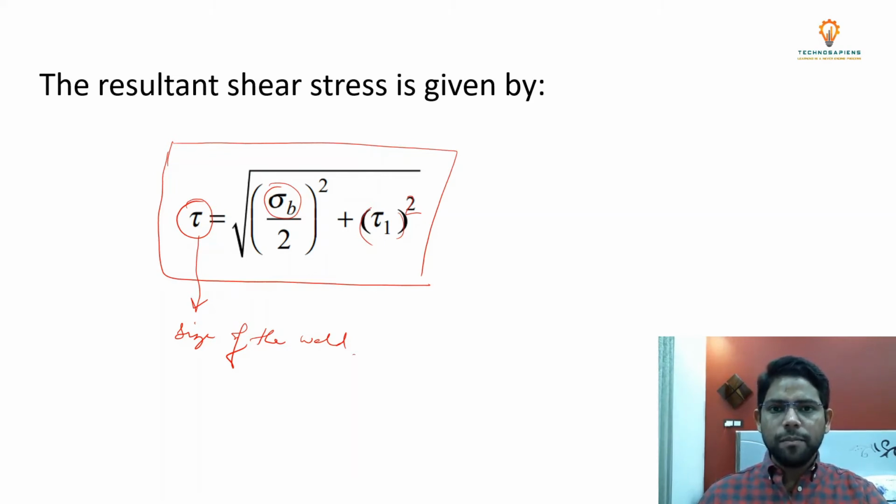If the load is in plane, that means there will be primary shear stresses and the secondary shear stresses developed inside the weld. Had it been out of the plane, then there will be primary shear stresses and the bending stresses. So you can see that with a slight mistake in judging what type of question this is, you will get a completely different answer, which will be wrong if you misjudge the question.